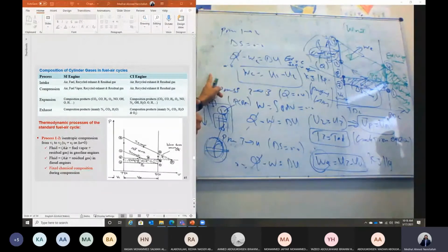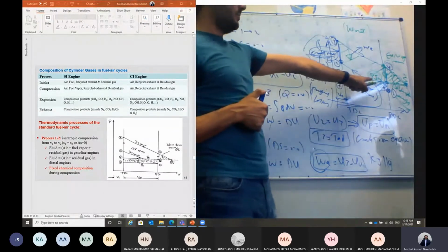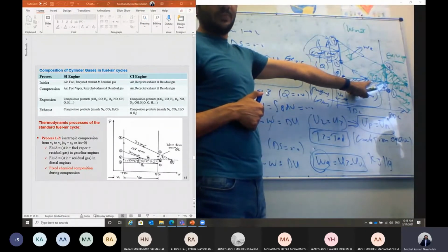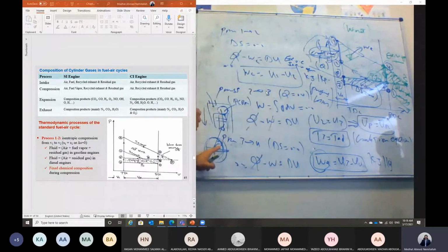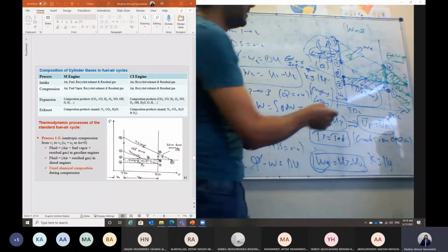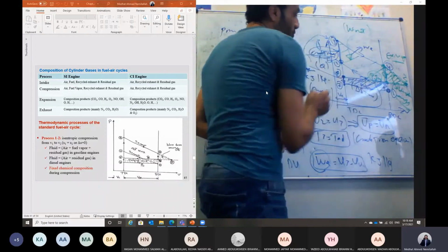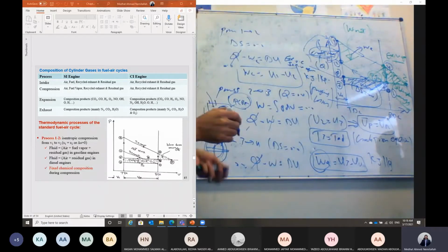Naturally aspirated means the exhaust leaves at atmospheric pressure, and while the piston is moving down during the intake stroke, vacuum pressure is created here, so the pressure is less than atmospheric. In this case, the pumping work should be a negative value, because it is coming from the crankshaft. It is not produced by the engine.